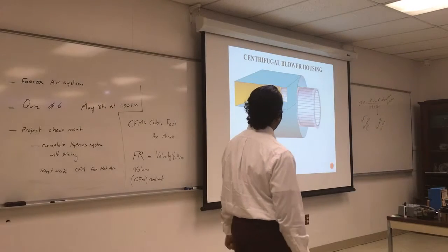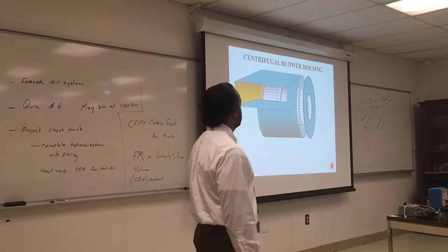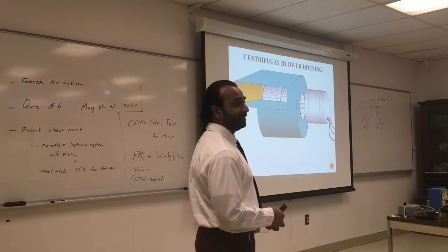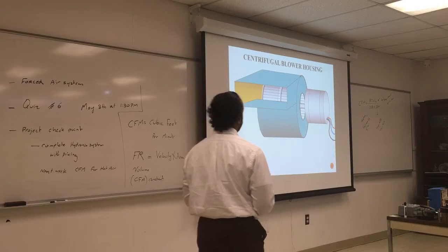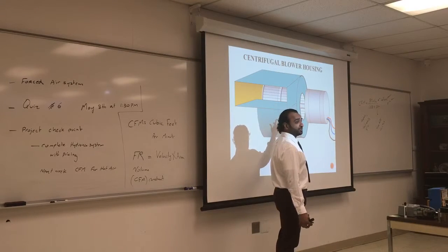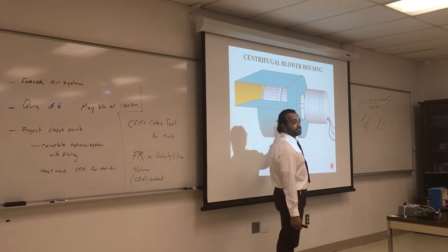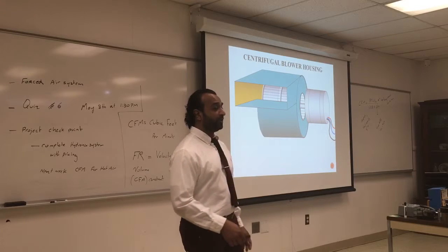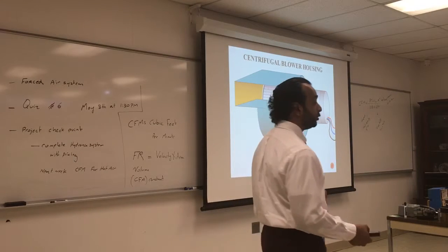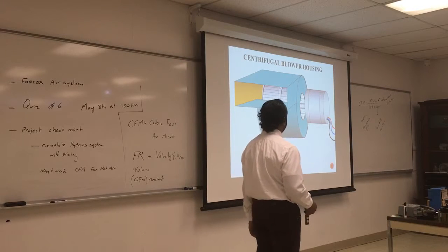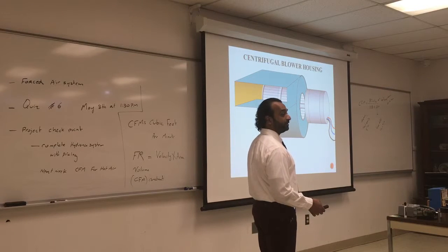This is the housing. I don't know if you did the lab where you have to take the motor out. It's very, very painful. Mini splits are also in central air systems. Taking this out is very challenging. But these fans actually do go bad. If anything goes bad, it's the fan, or sometimes the bearing. It's better sometimes to have the motor not attached to the wheel, which makes things easier.